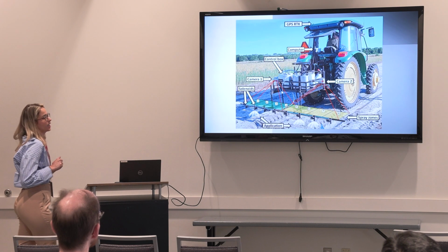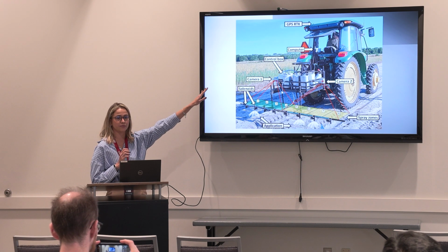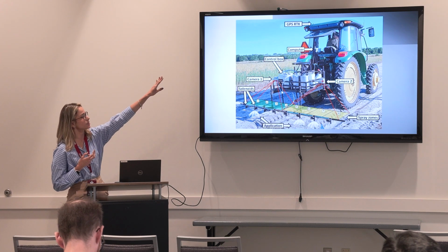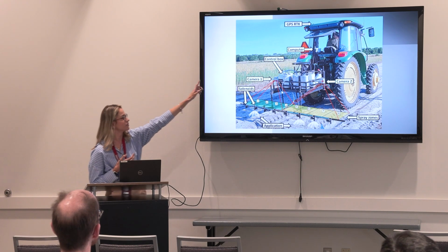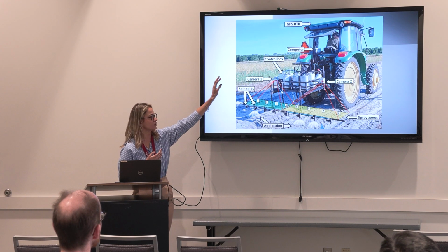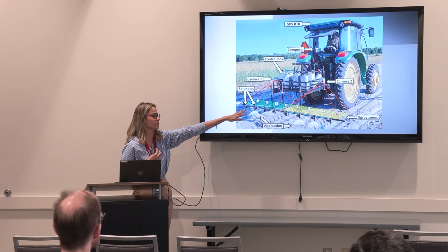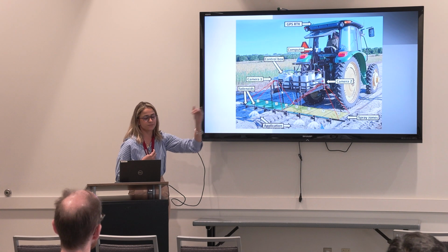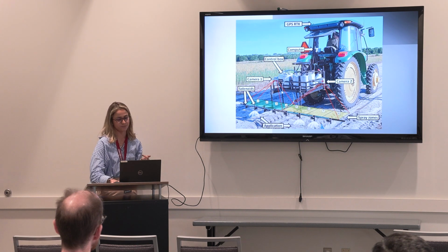And here is how you have the system. You have the computer that is inside of the tractor cabin, just because the Florida summer can be really hot, so you're trying to avoid damaging this computer. You have the GPS on the top of the tractor that gives us better signal, and then you get the speeds. You have the control box of the computer, and for this case, 2 cameras. Each camera is responsible for 4 nozzles. So the left camera has the 4 nozzles here, and the other camera, the other 4 nozzles. And this time we had 8 nozzles commanded by solenoids from TeeJet.